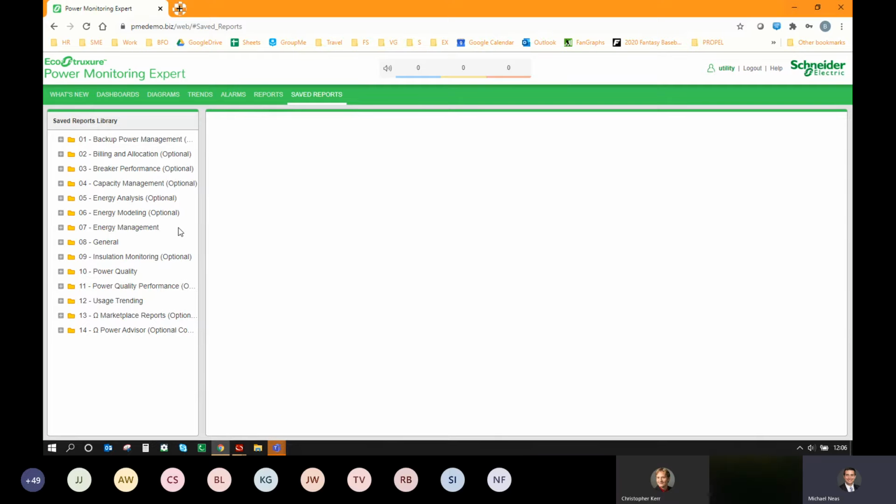We can also run things on event. So if you said, if X meter at a customer site sends back a sag, swell or transient delay for X amount of time, 5 minutes, 20 minutes, then gather all the events that may have occurred and send those out automatically in a report to these people or to this file location or wherever you want it to go, basically.